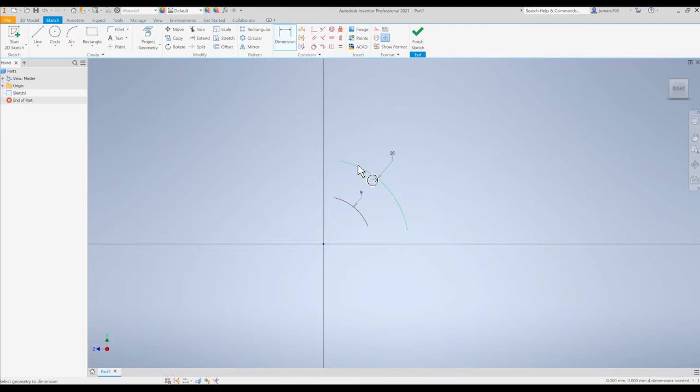Next, I would like to align these points vertically with our origin. So let's head up to constraints, selecting vertical constraint, selecting this. So notice here, as I select a vertical, notice the horizontal dotted line, which means in this orientation, we will be doing a horizontal constraint.